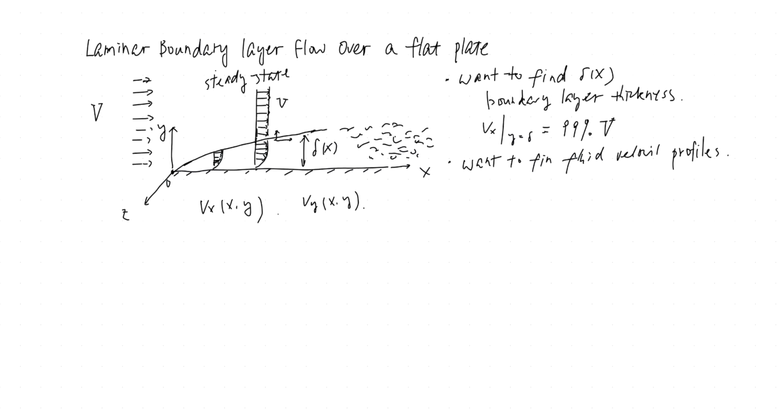But now we have Vx and Vy. If we use momentum balance along the x direction, we only get one equation. That means we can potentially only solve for one of them. But how about the other one? Vx is one variable and Vy is another variable. We consider these as two variables, so that means we need a second equation. And here is where the mass balance comes in.